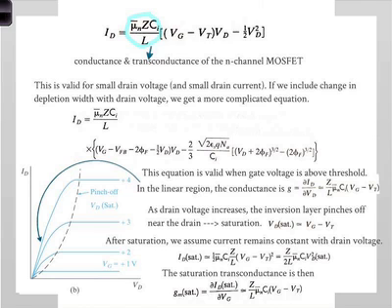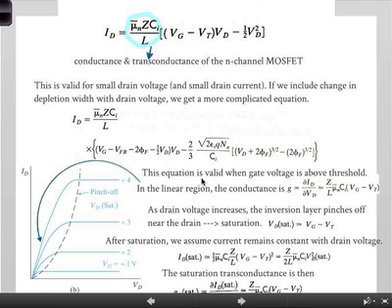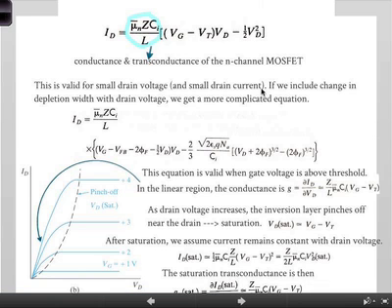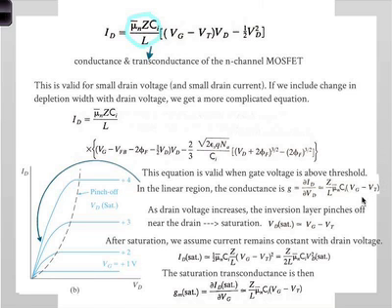In fact, it will become highly simplified. So a few things to consider in the linear region, where the transconductance is essentially the slope of this curve, or in other words, the gain that you can gain by working the transistor under the linear region. It is essentially the derivative of the drain current with respect to Vd, and you get a simple expression like that. You can see that the transconductance is dependent on the gate. So the higher the gate voltage, I can get higher gain, if my input was the drain voltage.